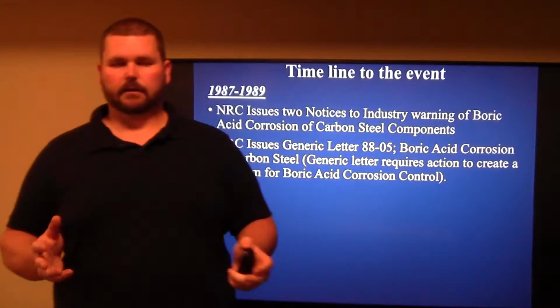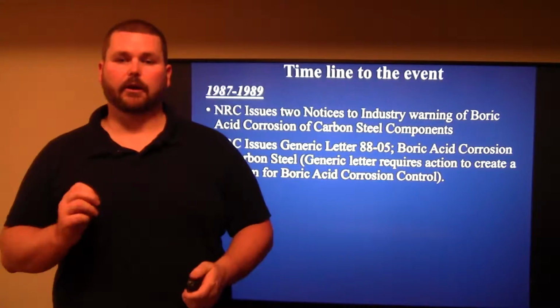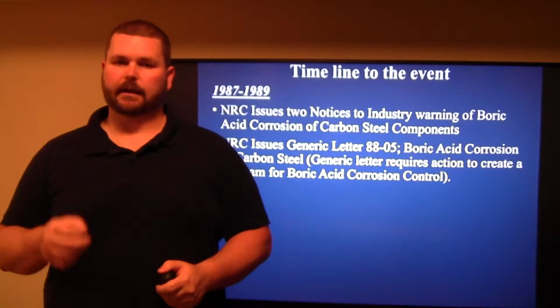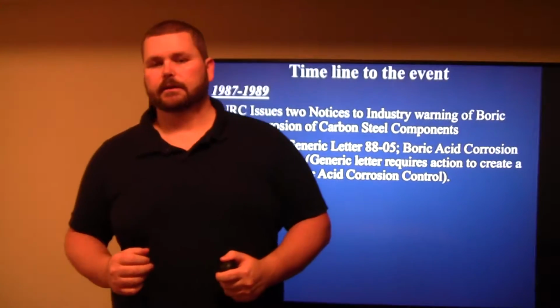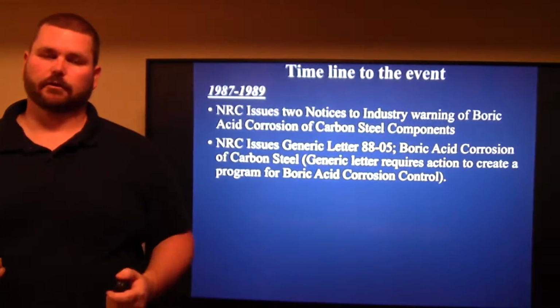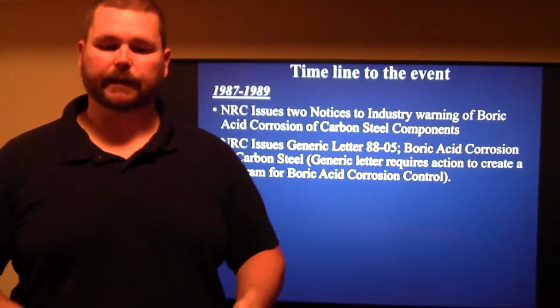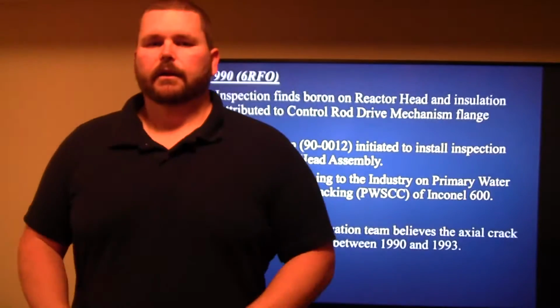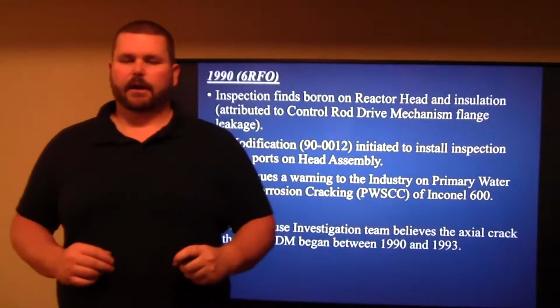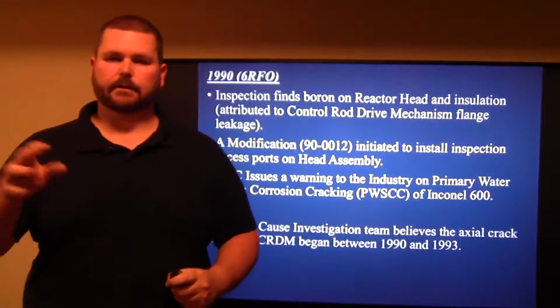And then, at the last part of it, they issued the third: generic letter 88-05, which required every single site to institute a program for boric acid corrosion control, saying, hey, how are you preventing boric acid and how are you inspecting for it? So they created their boric acid corrosion control program, and then they continue on.